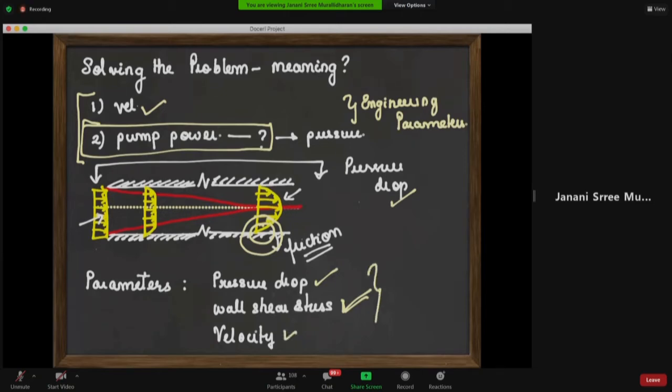So once you know all these three parameters, you can calculate the pump power that is required to ensure flow. I also mentioned how the velocity profile near the wall has a close tie-up. What is velocity profile? The change in velocity between adjacent layers. And that, in a way, talks about the wall shear, because there is something that's holding back my flow.